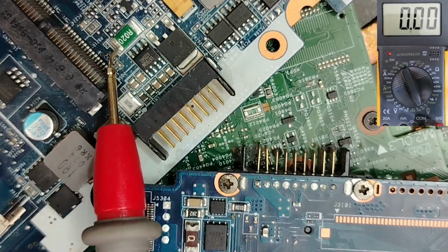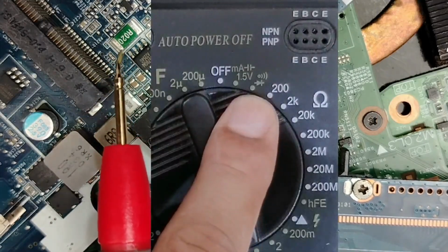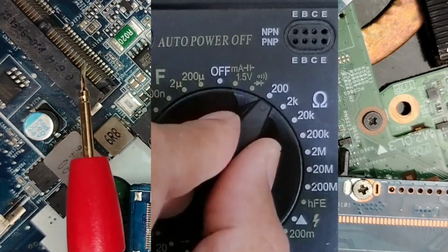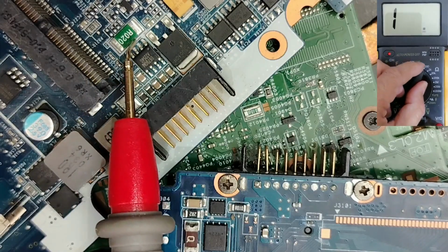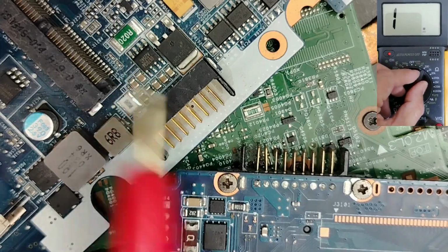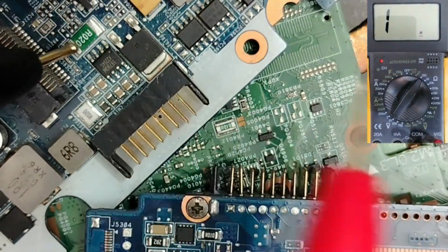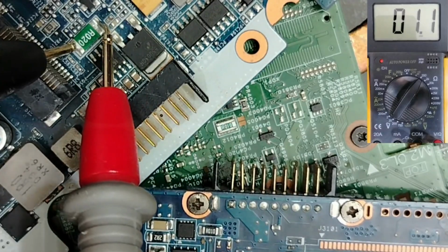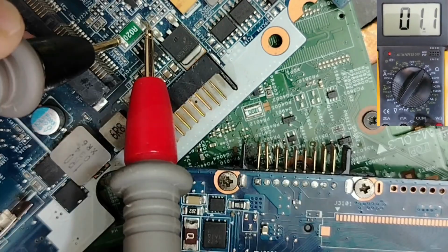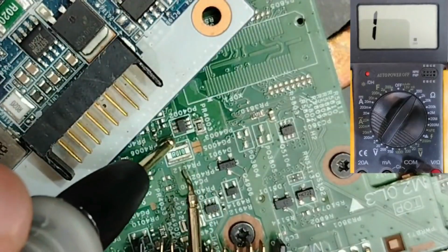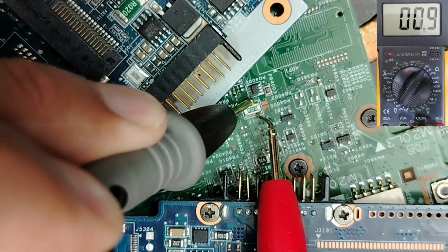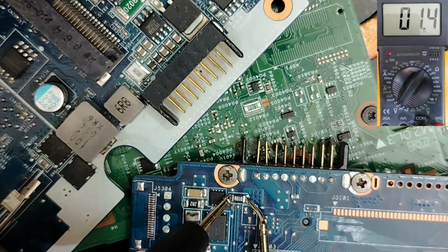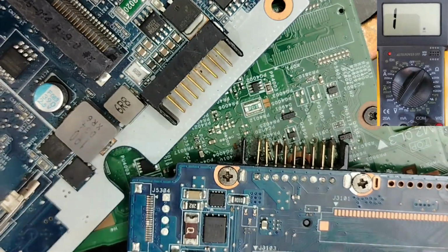So to test this kind of resistor, guys, you can just choose in the multimeter the continuity option or the ohm option. So let's choose, for example, the ohm option, since it is a resistor, and then we will choose also the continuity option. So we have here the ohm option. Let's check it right now. Let's begin with this one. We have 1.3 ohm. Okay, very low resistance. Let's check this one, for example, guys. 1.2, 1 ohm. This one also, 1 ohm. Okay, so about 1 ohm.